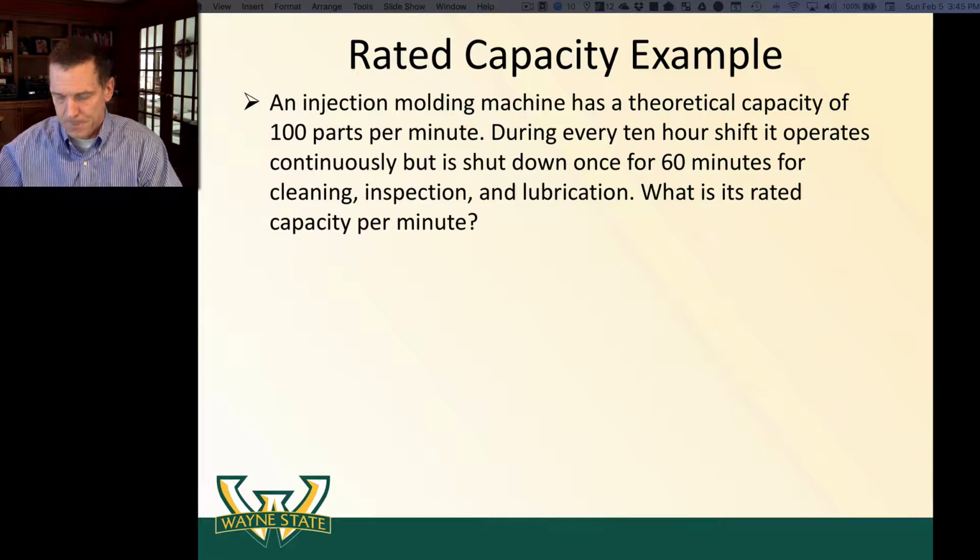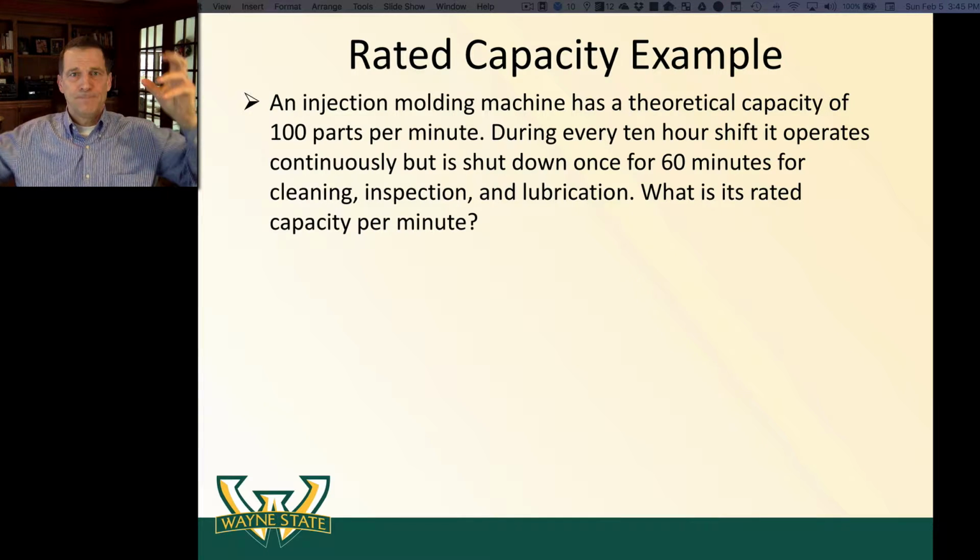Okay, so anyway, when we make plastic parts, one very common form is injection molding. We melt the plastic. It shoots through a piece of capital equipment at a certain pressure into a custom die mold, a mold that's the right shape so that the part can pop out. And we can use different molds with the same machine. We can change over and use that piece of capital, that injection molding machine, to make different parts because of the dies.